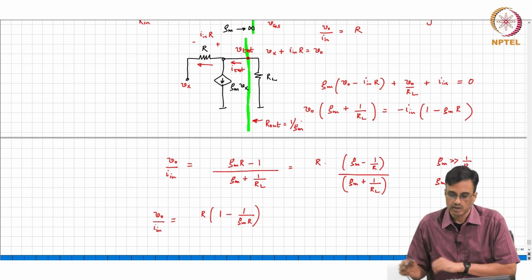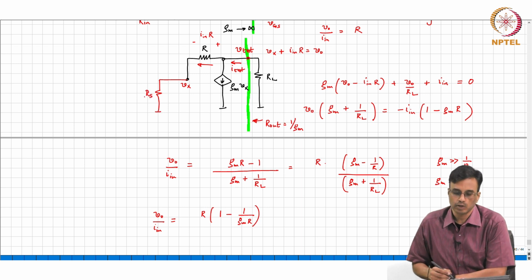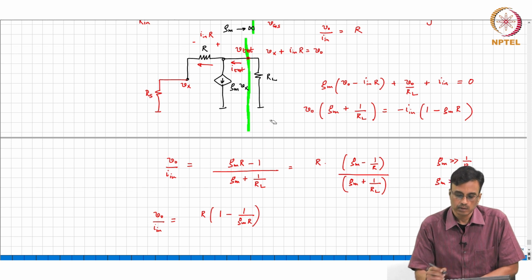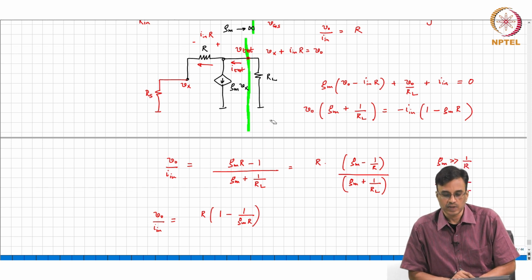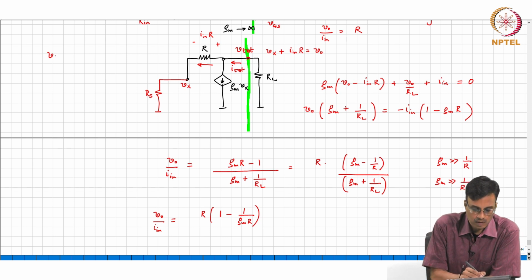All right. Okay. So, now if the input current source had an internal resistance, an output impedance of Rs, what comment can you make about the output resistance? Think carefully. What is Vx? Vx is Rs over Rs plus R times V test.